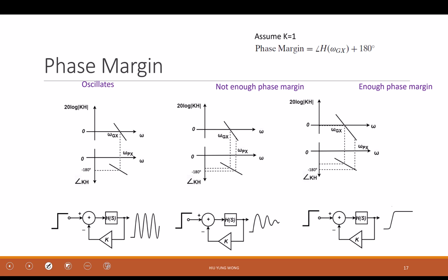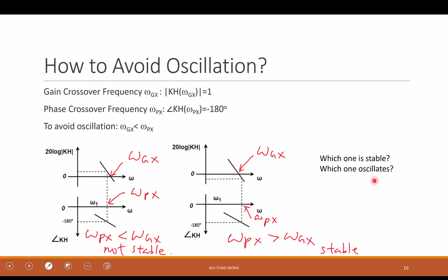Okay, so now, because we don't go too deep, we don't really do too much. So what is phase margin? You already know that in order to be stable, my gain crossover frequency needs to be smaller than the phase crossover, right? It means I want my gain crossover to be on the left of the phase crossover. And you can imagine as an engineer, nothing is abrupt.